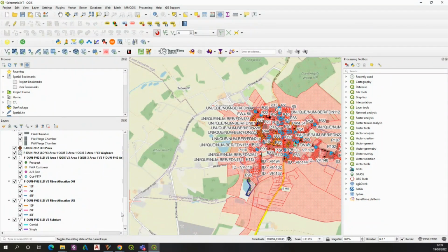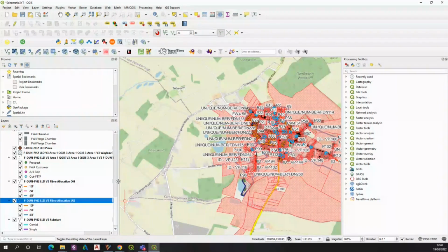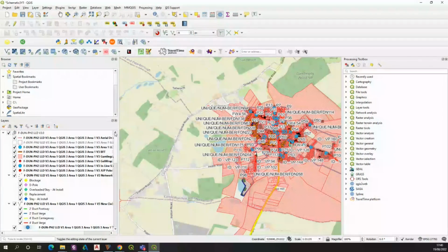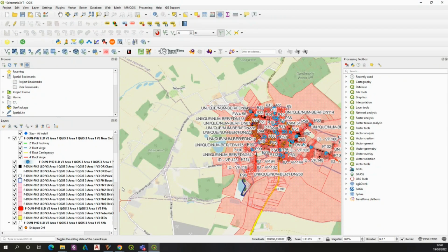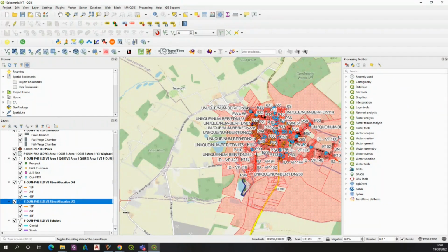And another group will be the line layers, line string to be precise, and it will be covered by fiber allocations, both overhead and underground. Alright, so we have pointed out 6 layers which will comprise our whole straight line diagram, and they are split by geometry. As you can see, they are already grouped. Occasionally, if it's a problem for you, you can move them out from that group, but you don't really need to do so, because everything can be done exactly from the step where we are.